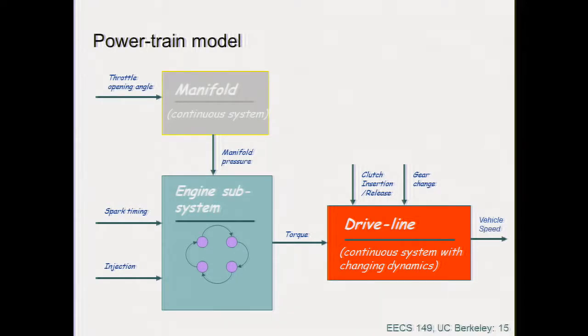Now, ideally, this explosion occurs when the torque is being generated. It's the so-called expansion phase. It's only one cycle of the 4 cycles. Only one phase where you get torque, for every single cylinder. Out of 4 phases, just one. Now, the other ones correspond to the change of phase, right? So you go compression, boom, expansion, exhaust, aspiration: compression, explosion, throw out the bad stuff, and suck in the new gas, right? So 4 phases. That's what we need to know, the 4 phases.